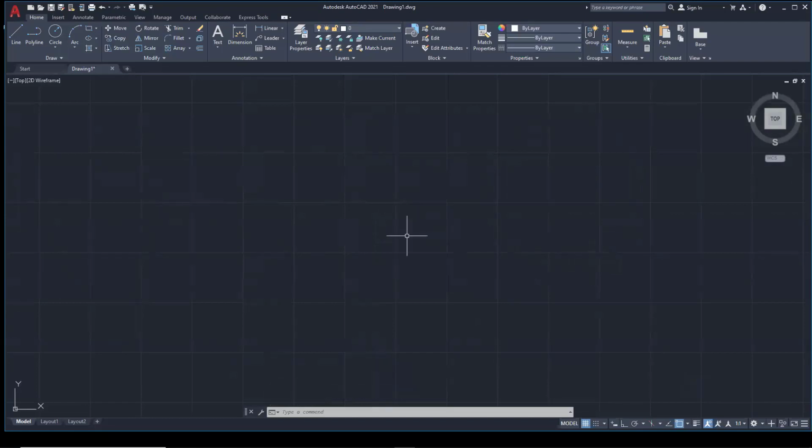All right. Another thing that AutoCAD will do is dynamic input. I have my dynamic input set off right now. When you start AutoCAD, yours may actually be turned on. I'm going to go into the line command and start to draw a line. I'm going to turn my dynamic input on, and I toggle dynamic input on and off with the F12 key.